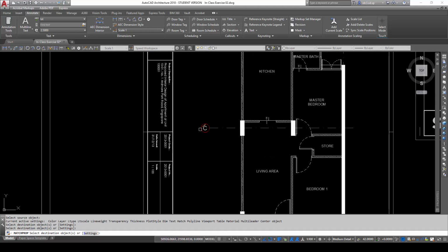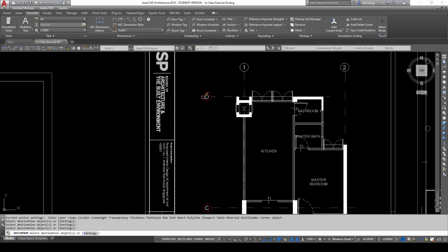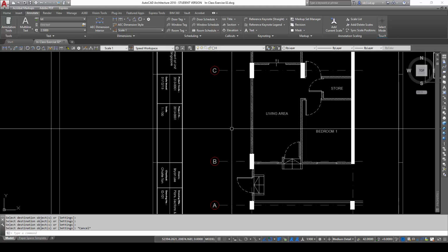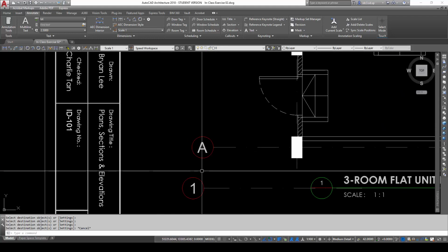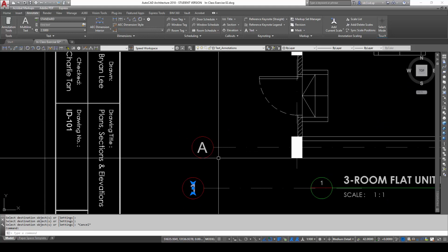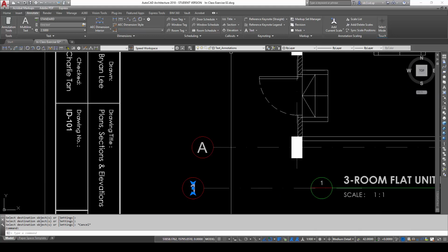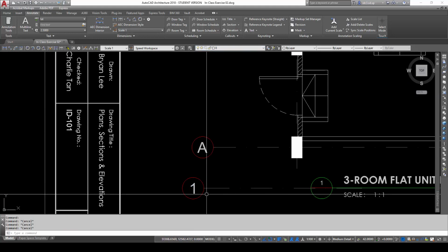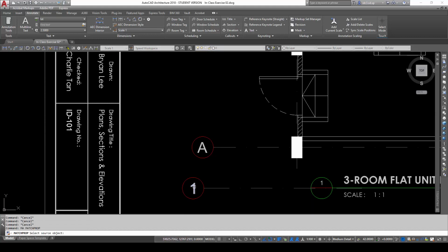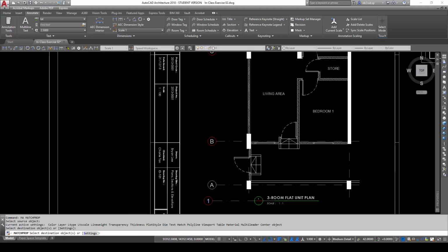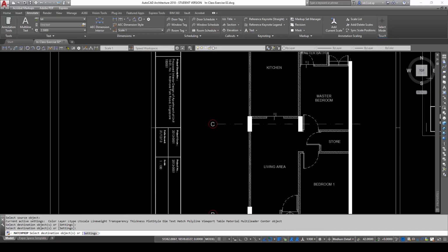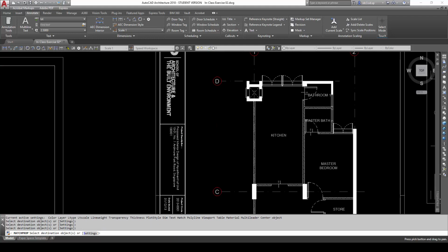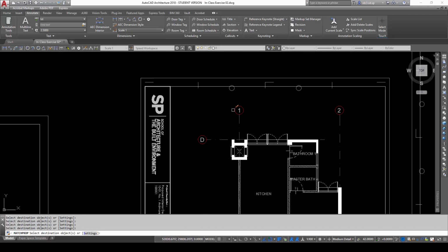The colors actually decide the print width or the line width of the lines. So I got to be really careful with it. And I'm not too sure also what layer this actually is in. It's in the text annotations layer. So I'm just going to play it really safe by just rematch propertying it again this way.